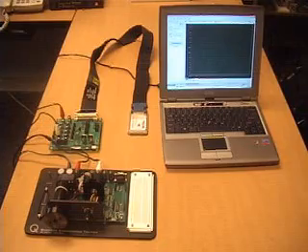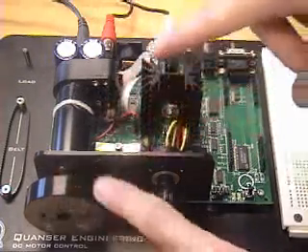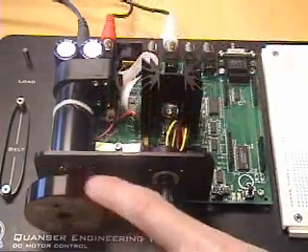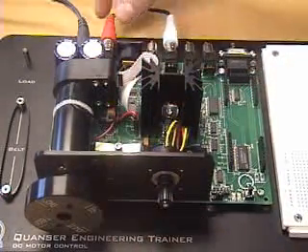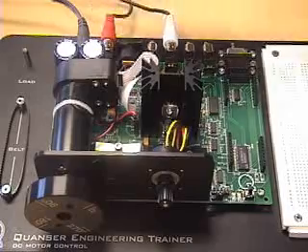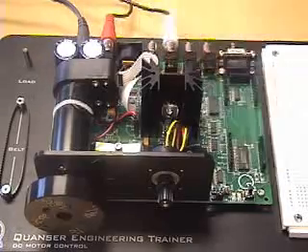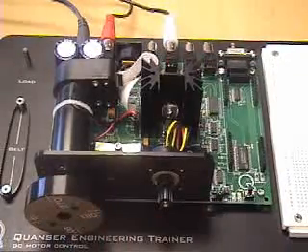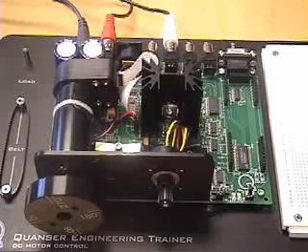on the PC. The tachometer, as I spin the motor, essentially will output a voltage that's proportional to the speed of the shaft. And the input voltage that I have in, again, is coming through basically a power amplifier, and that controls the speed of the motor proportionally to the value of the voltage coming in.